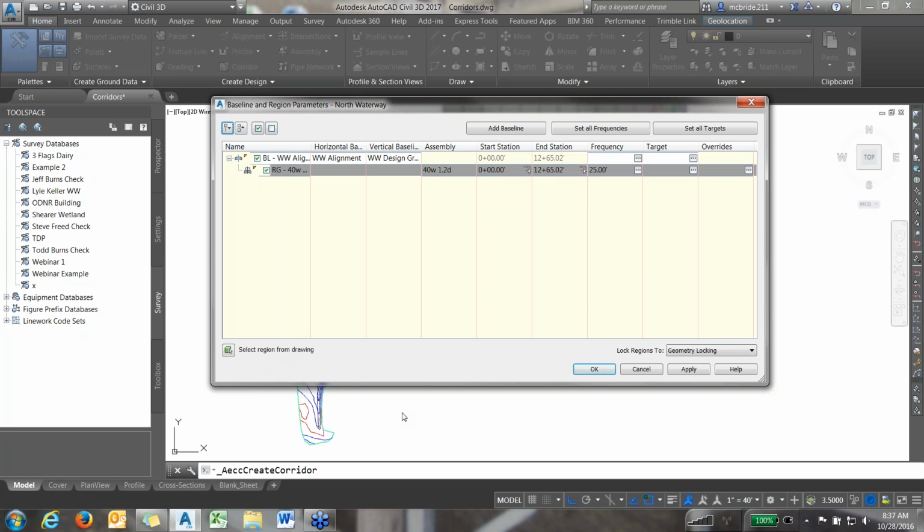No, I'm sorry. This goes into step 2. So this box pops up in the previous dialog box. At the very bottom, there's a check mark box that if I uncheck this wouldn't have popped up. But I always want this to pop up because I want it to remind me that if I have any other waterway sizes that I want to add to this grass waterway, I can do it right here, okay? But since I'm only doing one grass waterway size, I don't have to do anything here.